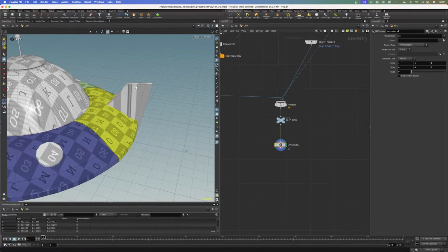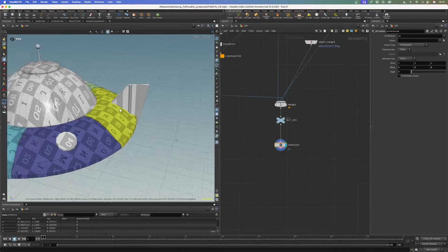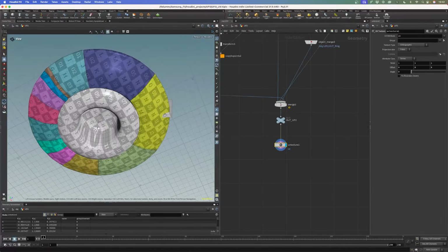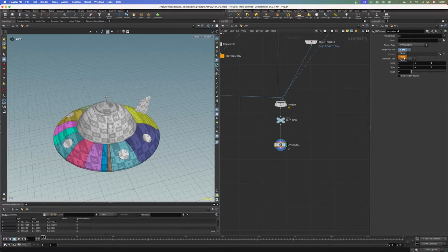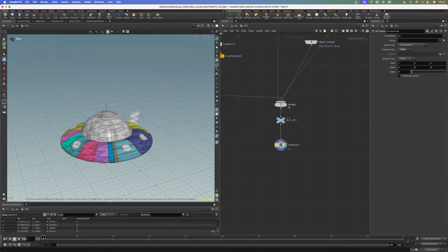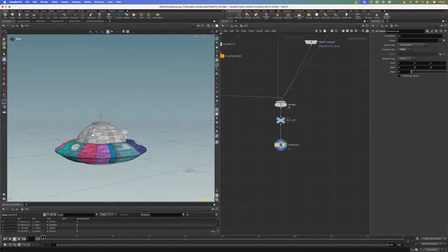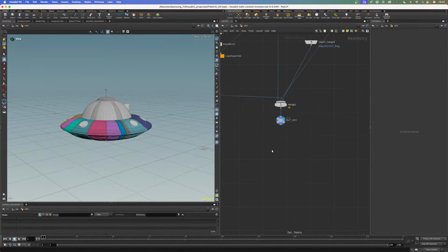areas like here, which are also really straight in the Y direction, it doesn't work really well. We could try out different kinds of axes, like X or Z, but we will always have this kind of stretched UVs and they will just look weird in the rendering part. Okay, so let's abandon this and let's try out a UV project node.